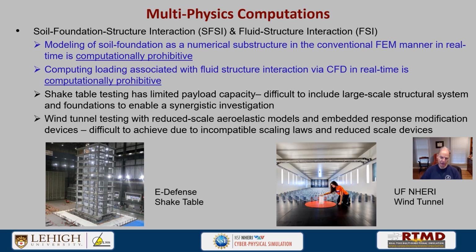Now, shake table testing may be an alternative. However, the payload capacity is typically limited, in that it's difficult to include the large structural system and the foundations to enable synergistic investigation. In terms of wind tunnel testing, we typically have to test reduced scale aeroelastic models, and having embedded response modification devices in these models is very difficult.